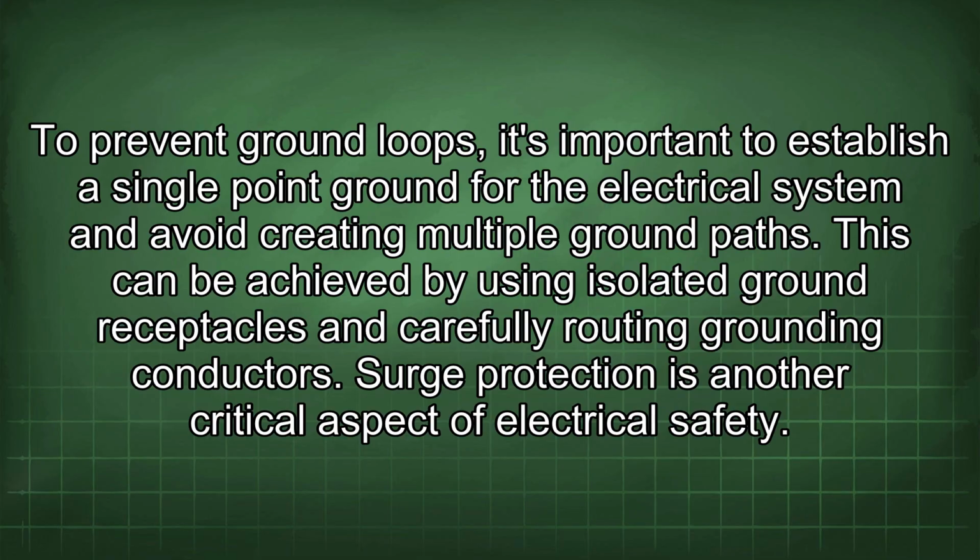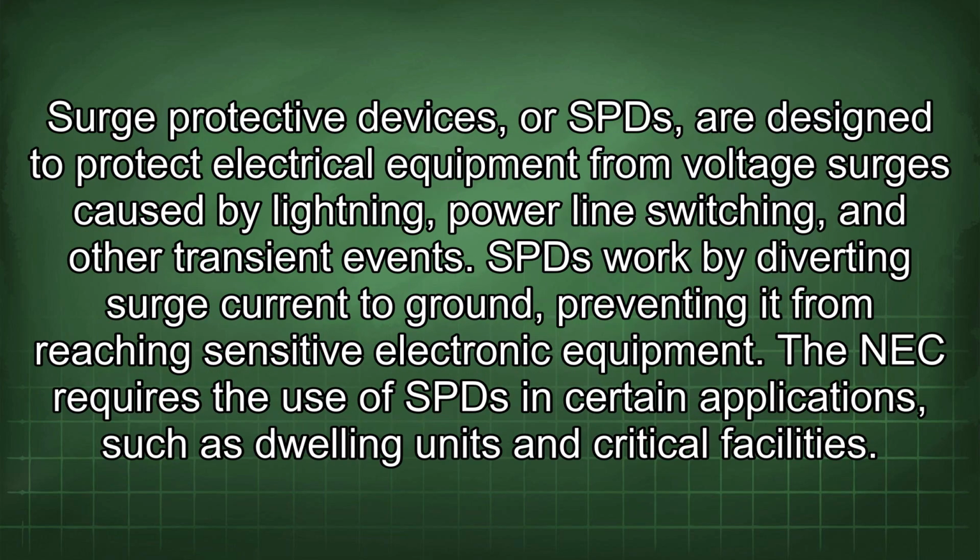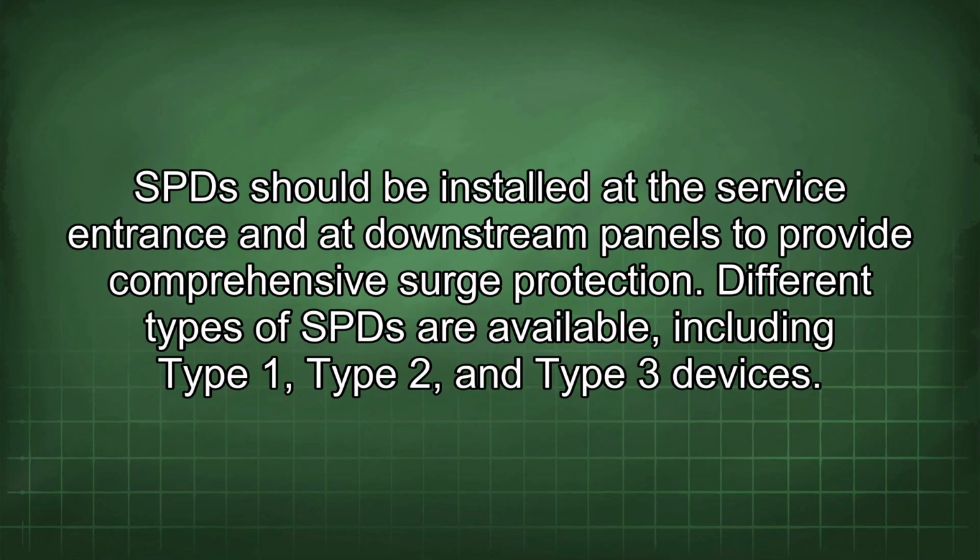Surge protection is another critical aspect of electrical safety. Surge protective devices, or SPDs, are designed to protect electrical equipment from voltage surges caused by lightning, power line switching, and other transient events. SPDs work by diverting surge current to ground, preventing it from reaching sensitive electronic equipment. The NEC requires the use of SPDs in certain applications, such as dwelling units and critical facilities. SPDs should be installed at the service entrance and at downstream panels to provide comprehensive surge protection.